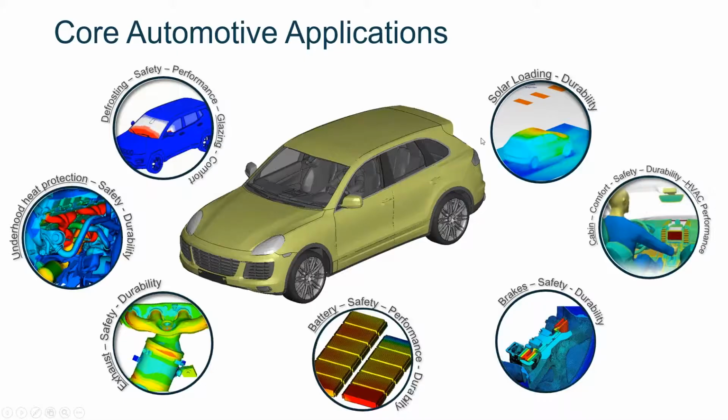As a background, I'm showing here the typical applications we automotive engineers face in terms of thermal management. It usually revolves around safety, like looking, for example, in the underhood compartment, that there is no overheating after a soak, or looking at brakes, that you don't have your brake fluid boiling.